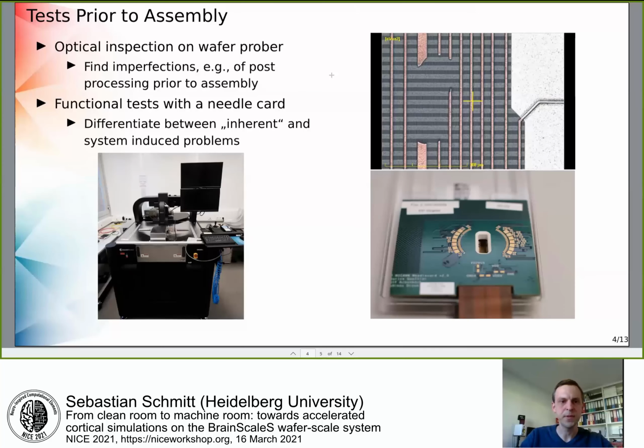assembly process? What we can also do here is that we attach a so-called needle card to the chips and then do individual tests of the functionality of the chips. And this is then using the same software suite as the full system, but only attaching individual chips.